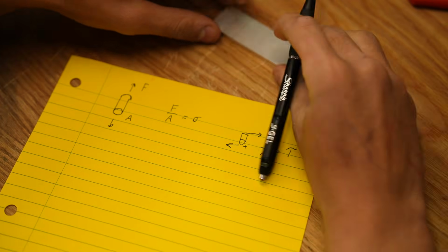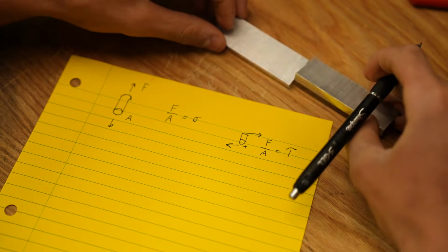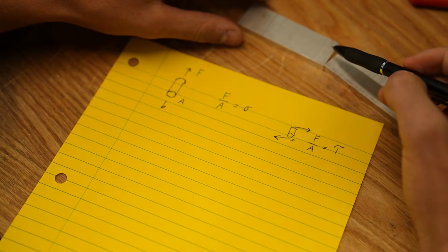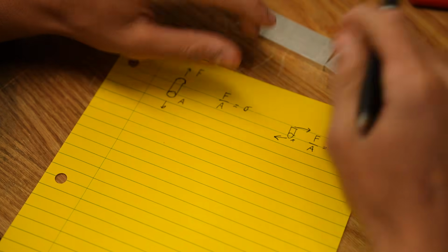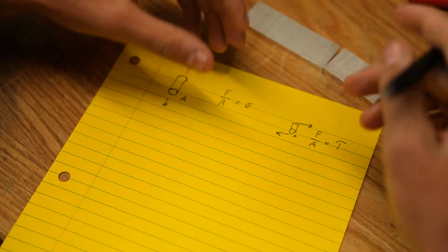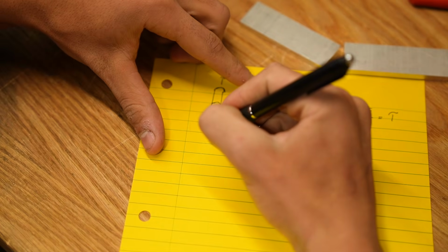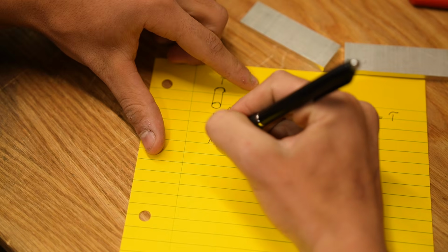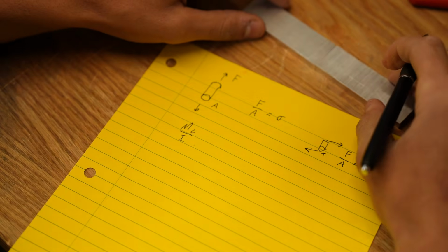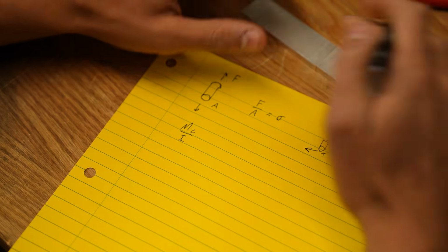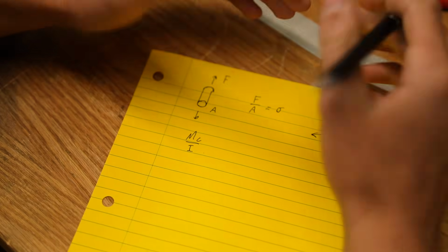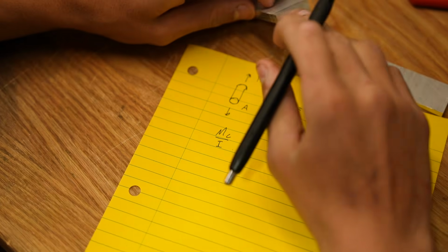Next, we're going to analyze bending and torsional stresses. Bending creates a normal stress in the very top of the beam. There's a compressive stress on the bottom, but the failure mode of tearing is one of tension. The equation for that is going to be MC over I, which is the moment in bending multiplied by the distance from your neutral axis, which is like the middle of your beam, divided by I, which is a property of the cross-section of your beam.